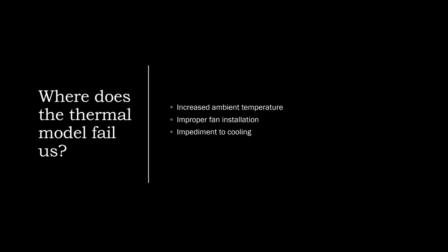And if things like sawdust or kaolin, other materials of a powdery-like substance can form together to block the heat dissipating from those fins, that is also going to affect the motor heating and make the thermal model that much more inaccurate.